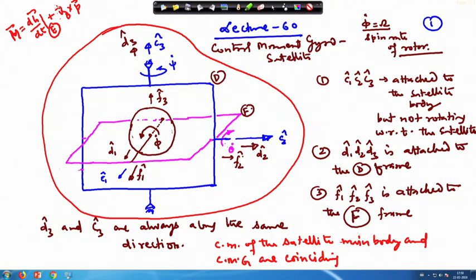So, unnecessarily we do not have to carry this term if we assume this. This will simplify our whole process a little bit, and it is always possible to fix the other components such that the center of mass of the rest of the satellite and the CMG coincide.